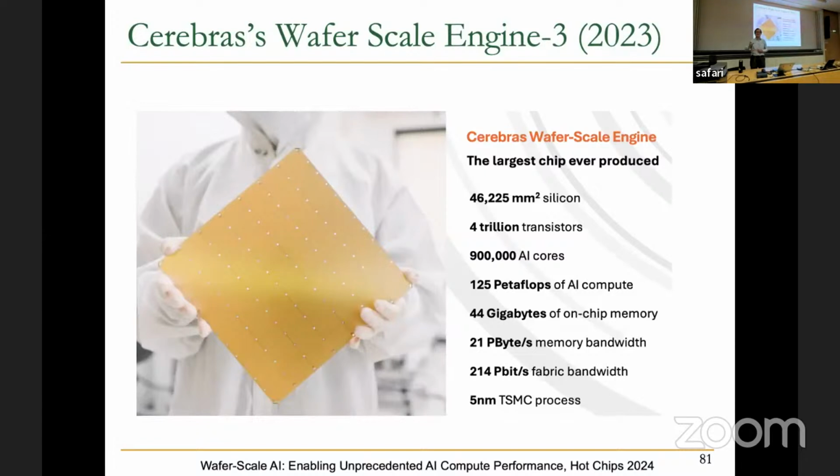It's having difficulties in justifying its cost. So the cost of a transistor is not reducing as much as it used to. But people are still packing more transistors on a given millimeter square. And still there's some cost reduction, but not huge. Okay, anyway, but basically you can see that they can have 44 gigabytes of on-chip SRAM coupled with processors. These are SIMD processors, single instruction multiple data processors, in this. So it's a lot of memory, but it's not enough memory.